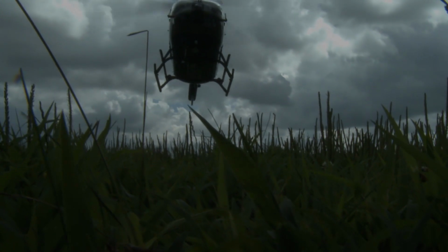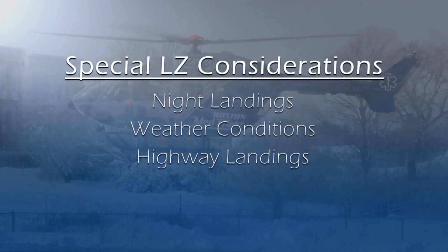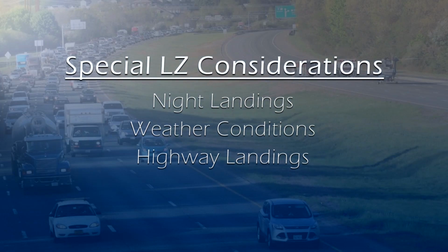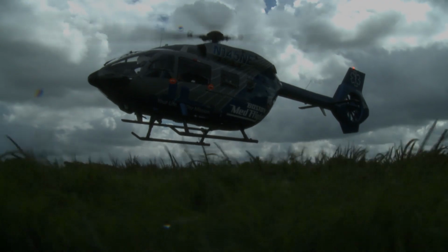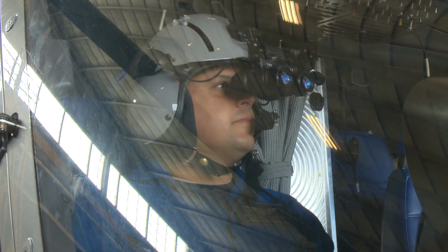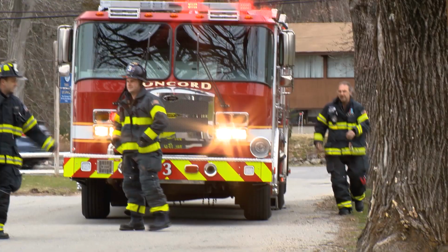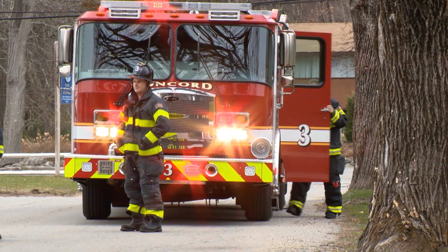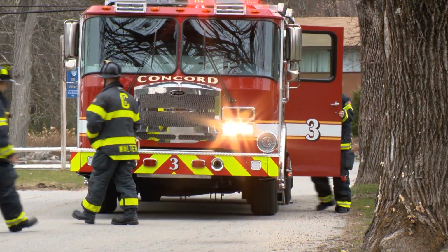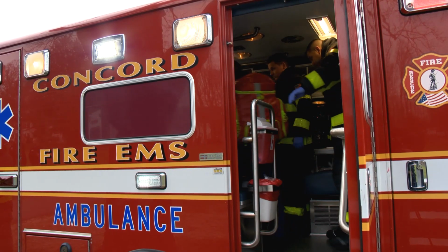This final chapter focuses on special considerations, including night landing, weather conditions, and highway landings. If a nighttime aircraft landing is required, there are a few things to keep in mind. All Massachusetts helicopter air ambulance pilots wear night vision goggles. Artificial lighting can be very distracting or even blinding to the pilot. LZ Command should be aware of high-intensity lights that may be in the LZ area.